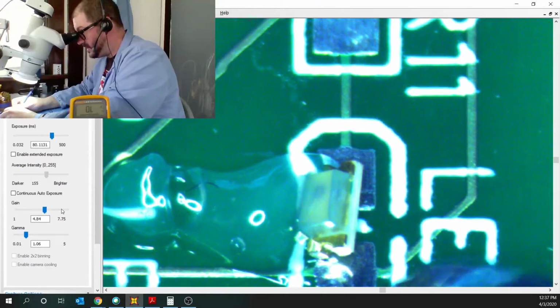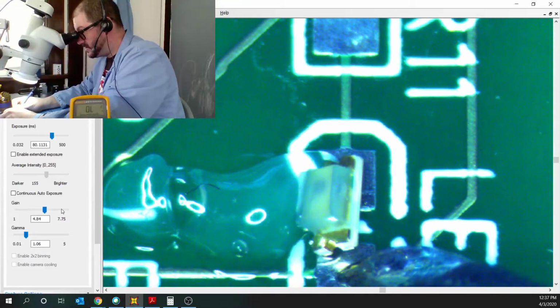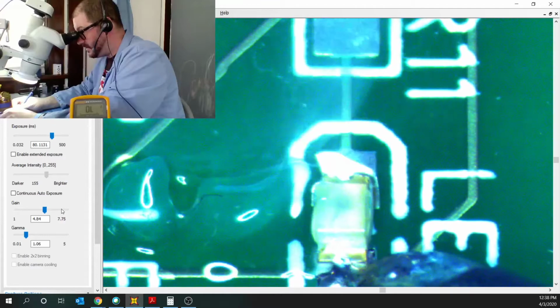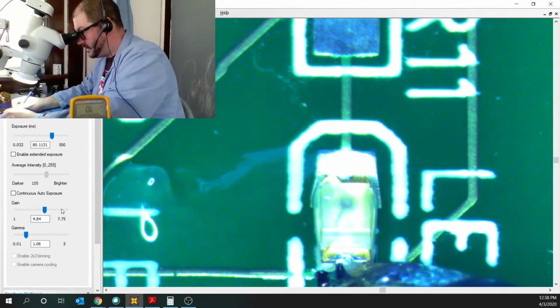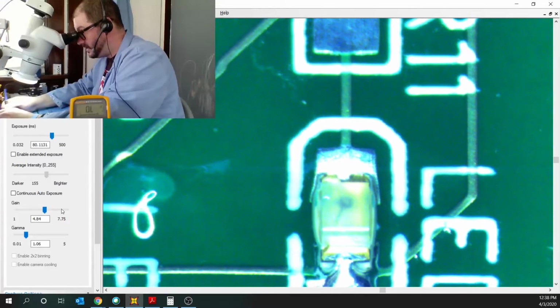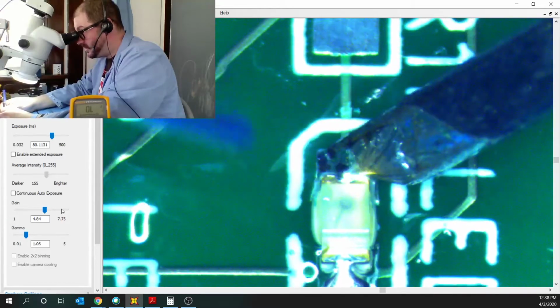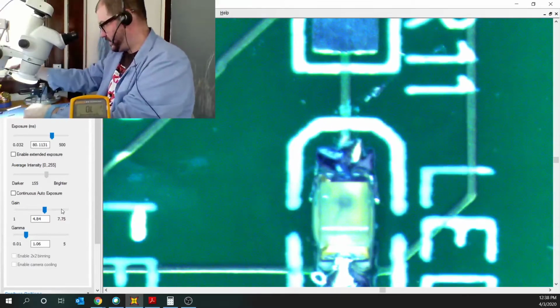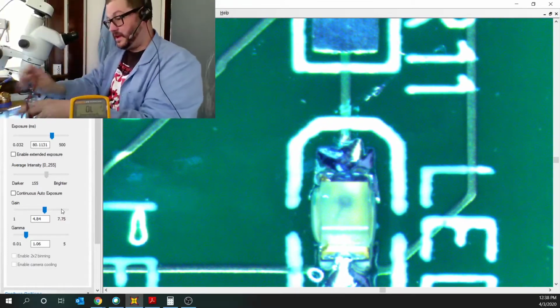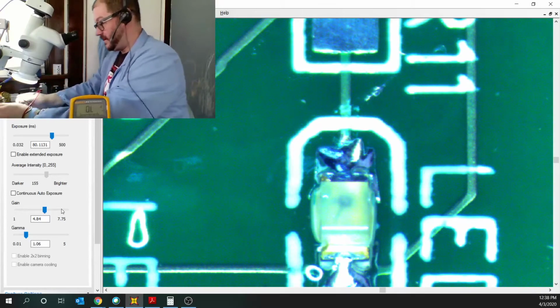I'm going to come at the fluxing agent, which is currently on the pad, and that has actually been nicely placed along with that LED, so that sticks it there. And I'm going to use the rest of the flux that's on the other side here to tack down. I got a little bit of a stalactite, but I'll fix that here. And then test this LED.